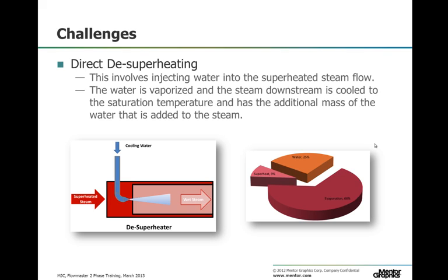First, as per the Rankine cycle, superheated steam is thermally more efficient than saturated steam for powering turbines. Secondly, wet steam can cause formation of water droplets on the turbine blades. These droplets cause erosion of the blades, which increase friction and reduce the life of the turbine. Other benefits include higher pipeline velocity, which allows for smaller distribution piping systems, and the fact that there is no condensation in the piping systems, which eliminates the need and cost of most mitigation devices.